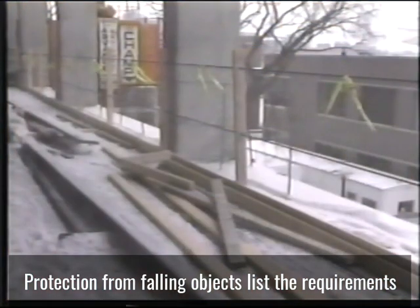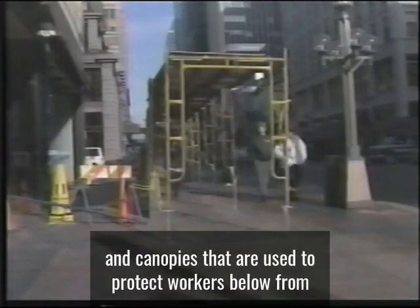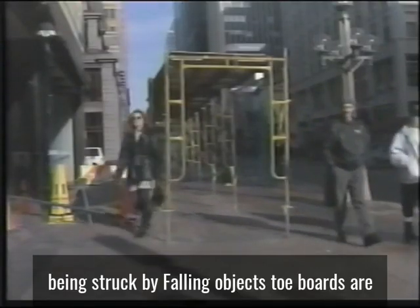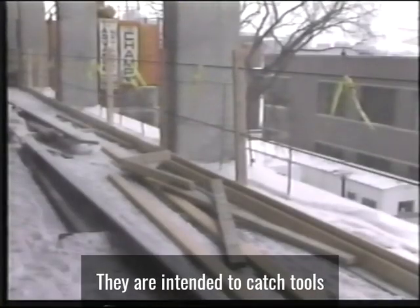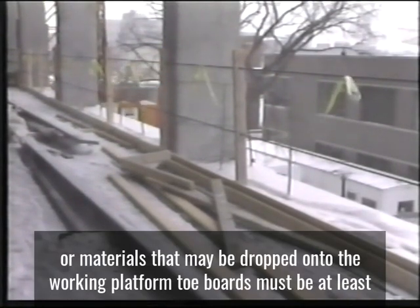Protection from falling objects lists the requirements for toe boards, guardrails, and canopies that are used to protect workers below from being struck by falling objects. Toe boards are required on the edge of those working surfaces where personnel, vehicles, or equipment pass below. They are intended to catch tools or materials that may be dropped onto the working platform.